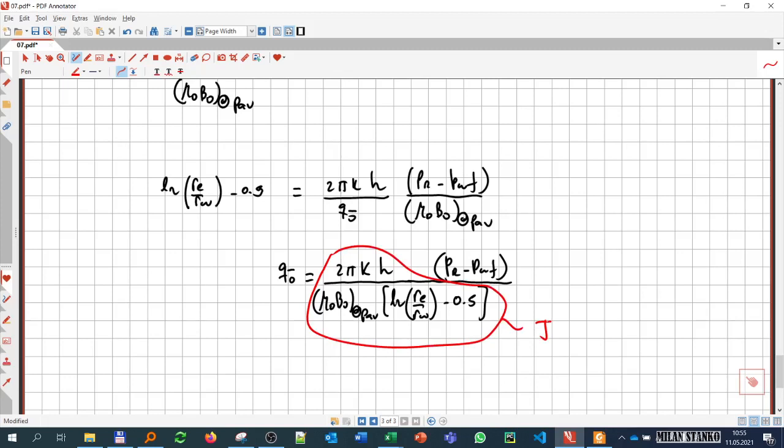And you see, it actually fits quite nicely with the previous. I have a J which is constant, relatively constant. That is a proportionality constant between the drawdown that I have here to the right and the rate of oil at standard conditions. The only thing is this one depends on the average, so it's at this average pressure and temperature. So this might not be constant. We will see in the next video how constant this is.